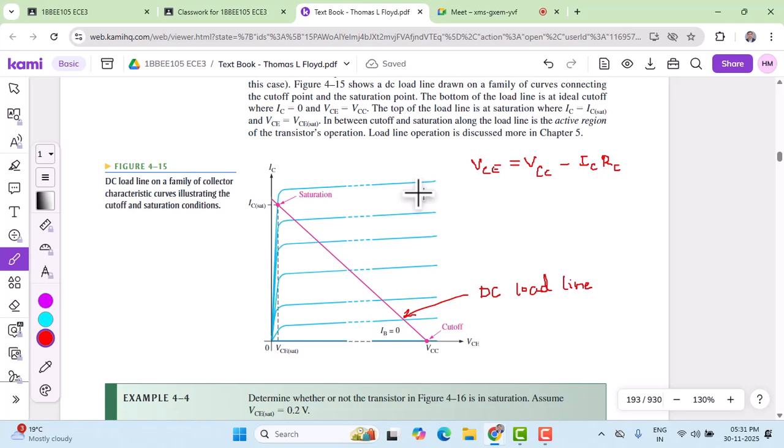Let's assume that the PD max given is 500 milliwatt. If this is the maximum power dissipation given for the transistor, then we should ensure that the product of VCE and IC does not cross this limit. If PD max is 500 milliwatt, and we assume the maximum collector current is 50 milliampere, then the collector emitter voltage should be in the range of A to B.